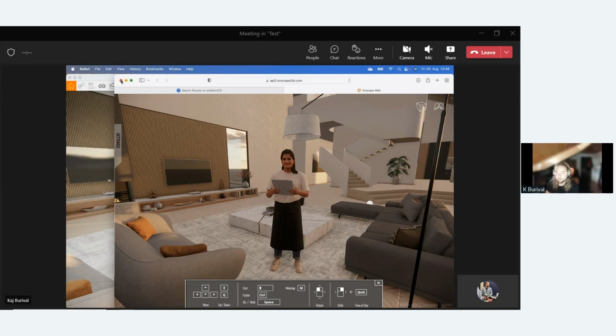But you have to keep in mind that some of those are sometimes made for offline rendering, which is the kind of rendering that does not care how long it takes for a single image. So of course, if you want to use multiple assets or multiple instances of the same asset, it's probably best to have a look at the polygon count. But yes, that is something that is supported by Enscape in general. Currently only on Windows. It's going to come for Mac as well, though.